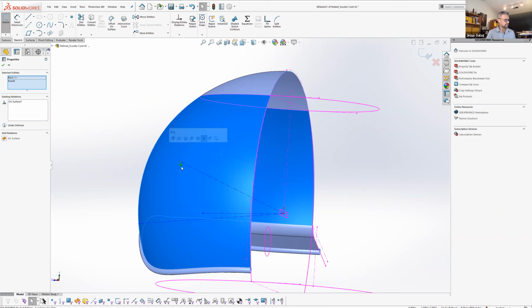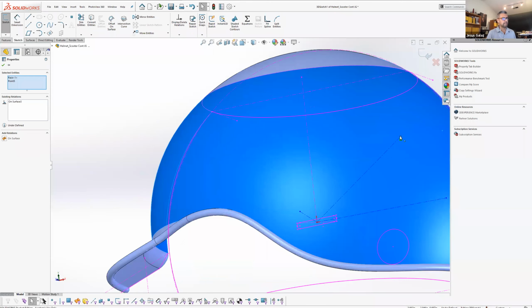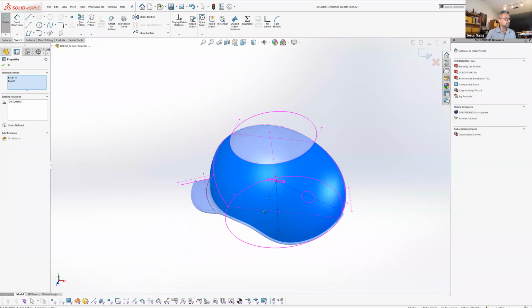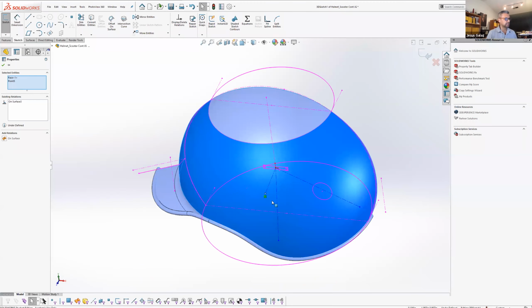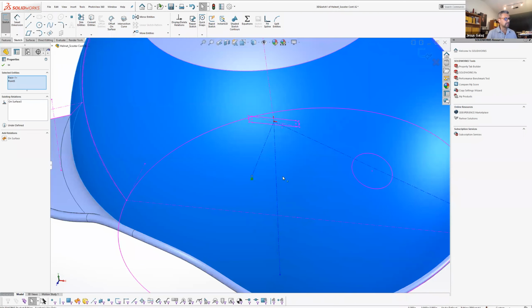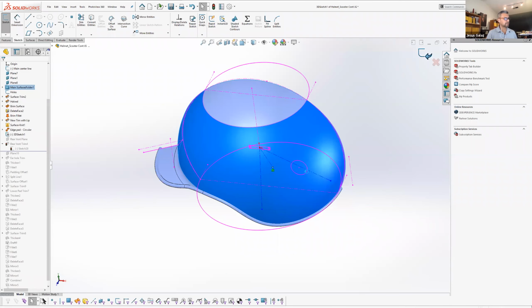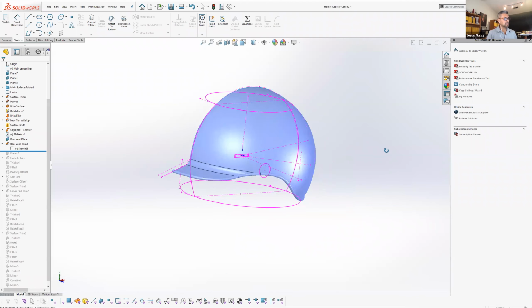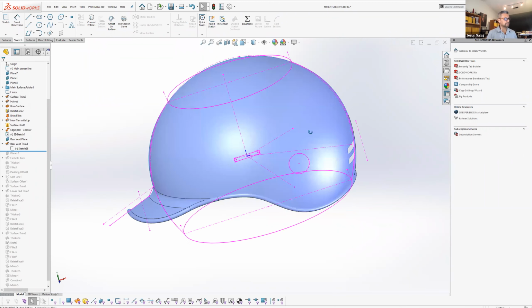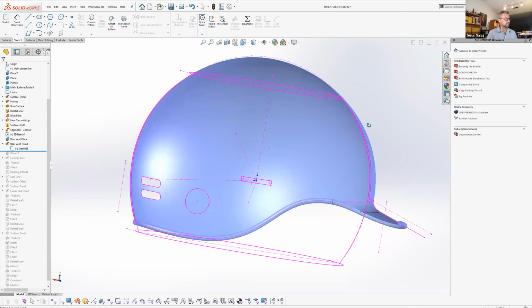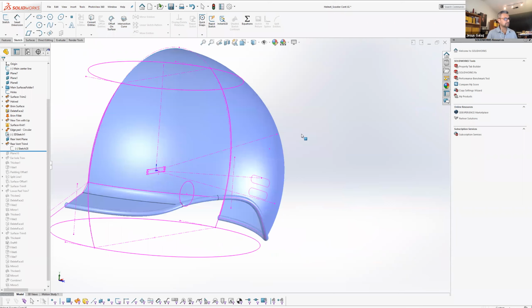So you just move that point around to where you need, let's say a vent point, maybe, or whatever it might be. Maybe it's a hole. Anything you want to project perpendicular to the surface, that's where you would put that sketch, or that entity. And then once you have that, you can see that it's in 3D there. It's perpendicular to that surface.